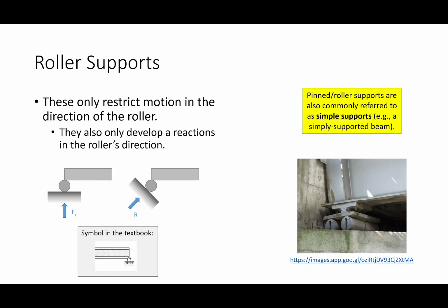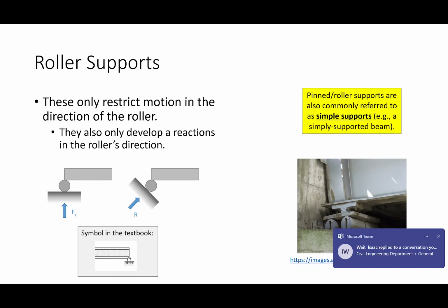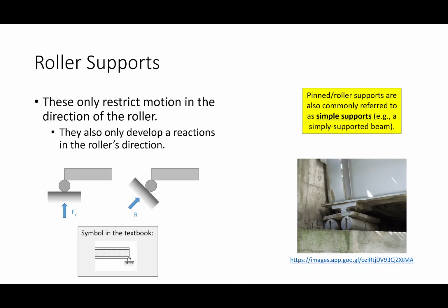You'll see in bridges fixed bearings and expansion bearings that allow that rotation. Instead of a straight hole, you'll have a slotted hole that allows it to move a little bit. This is probably more of a mechanical expansion bearing where it can actually roll. A lot of times in more modern bridge applications, the bearing system will be an elastomeric bearing.